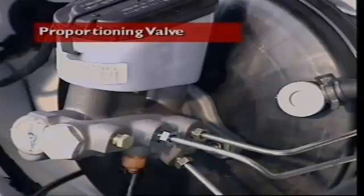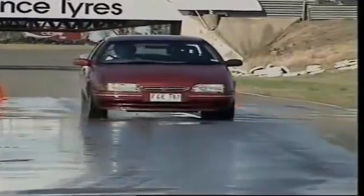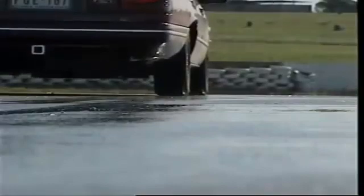This section examines the proportioning valve. It divides up the braking effort applied to front and rear wheels under heavy braking, according to how load is distributed across a vehicle. The effectiveness of braking force is determined by tire-to-road friction, and this increases as load increases.